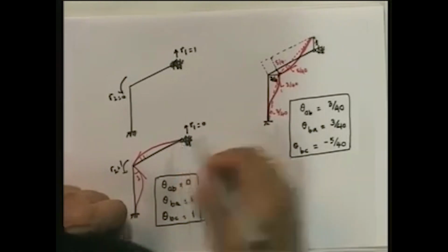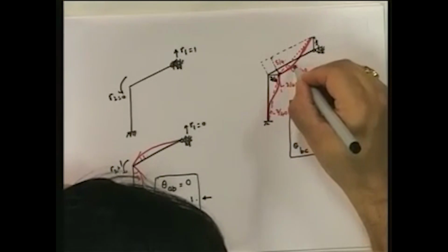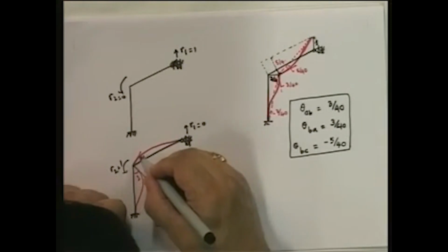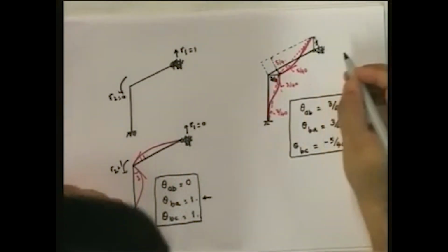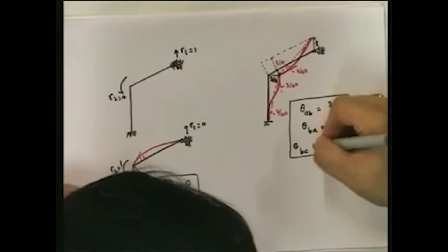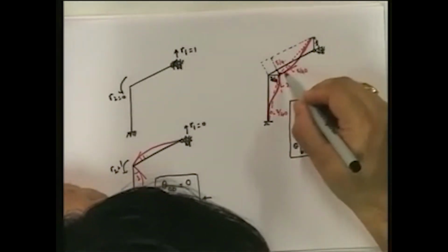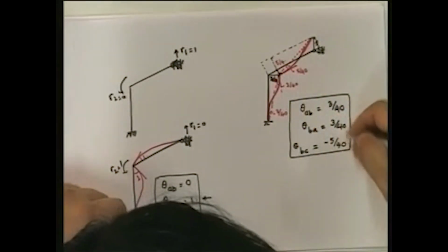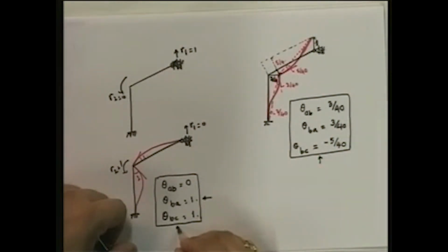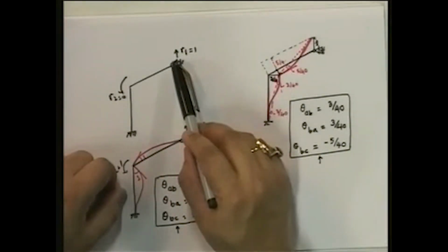Instead, you have zero moment. Okay, so in other words, in the earlier case it would have gone like this and gone like this because this cannot rotate. Here also this would go like this and then come like this because it cannot rotate. But as far as these values are concerned, they don't change at all because the tangent and the chord remain exactly the same. Okay, so therefore these things are not determined closely by the fact that this fixed roller has become a hinged roller.